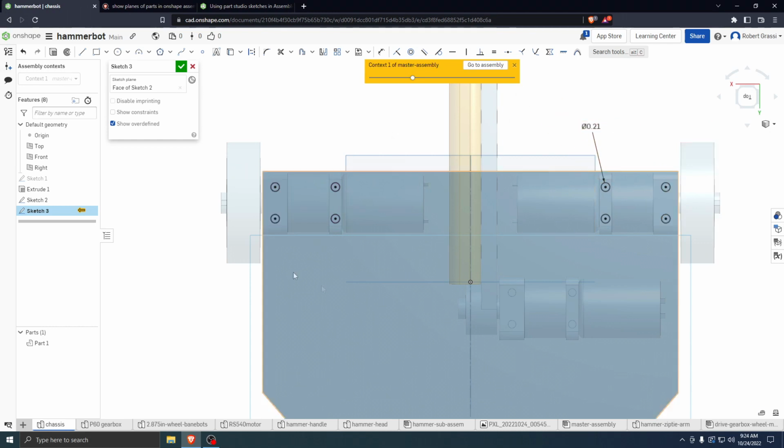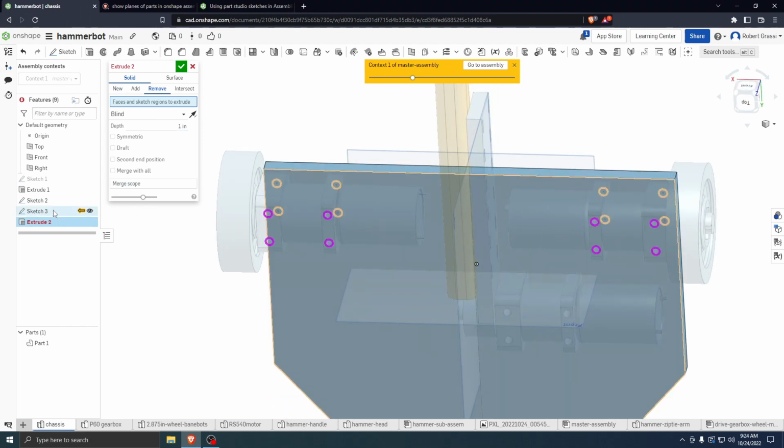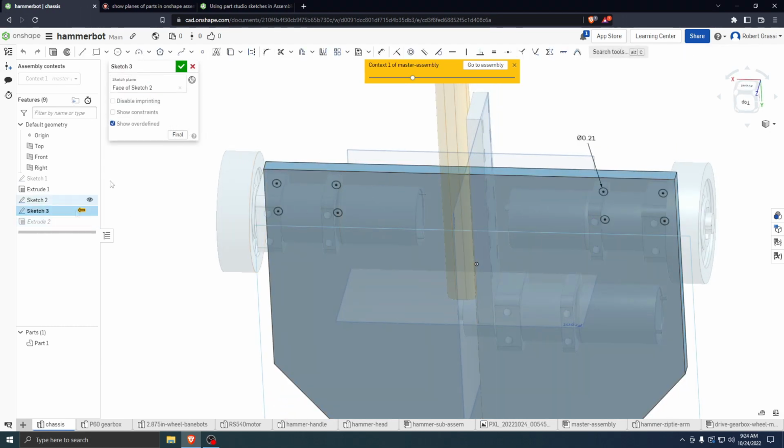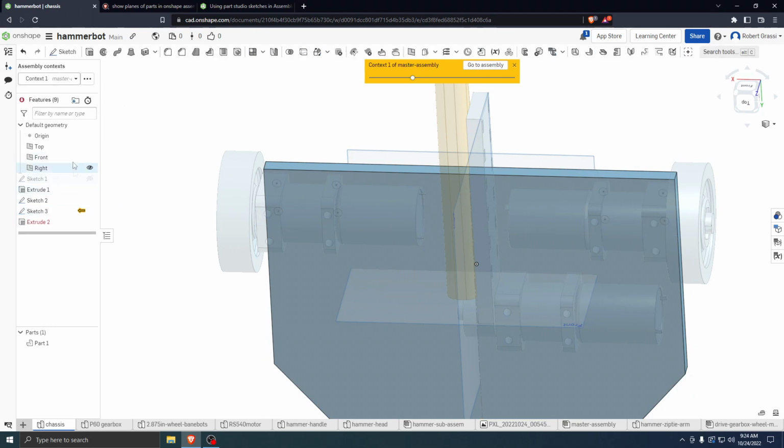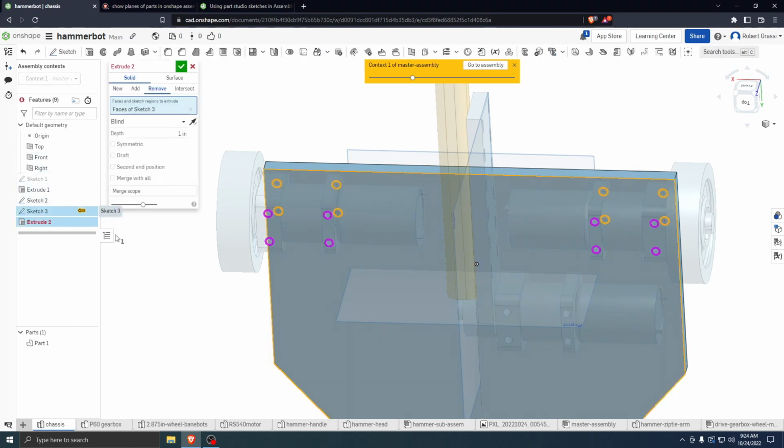So now if we wanted to change the size of the holes, we just need to change one value. We can go 0.25, and they change over here as well. So again, design intent, it's nice to group things together that are going to be the same. So we'll hit OK here. We're going to do our remove extrusion, and we're going to use our sketch. Okay. So we click on our sketch, and yes, we want to merge the scope.